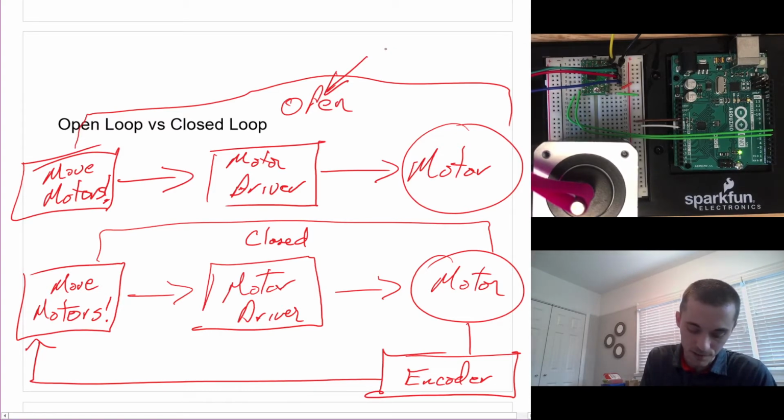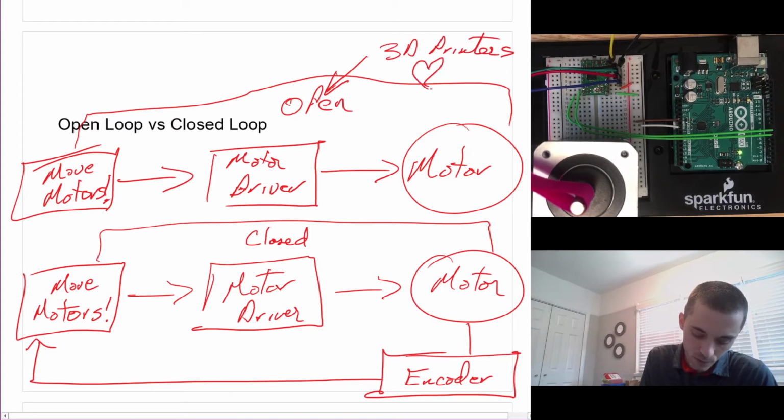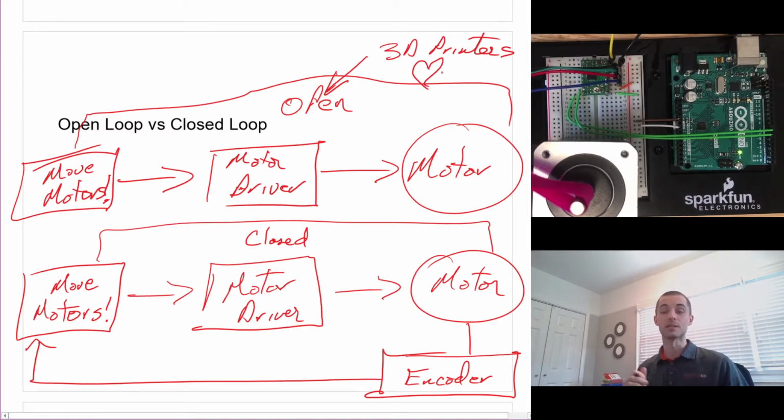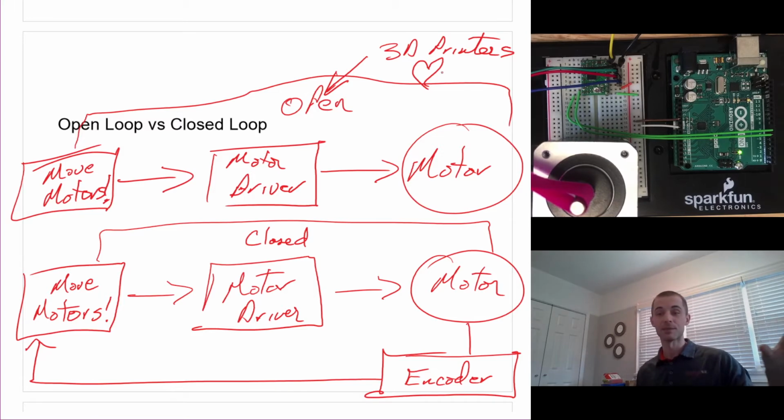This is the 3D printers. They love open loop control, right? Because if you try to work with almost any of the inexpensive 3D printers, let's say anything sub, I'm going to guess sub $3,000, you will be able to physically stop the device from moving and then let go, and it will have no idea that you just prevented it from moving.